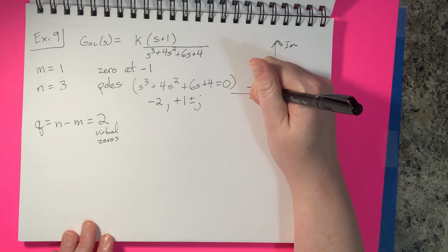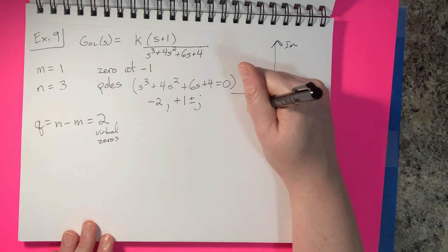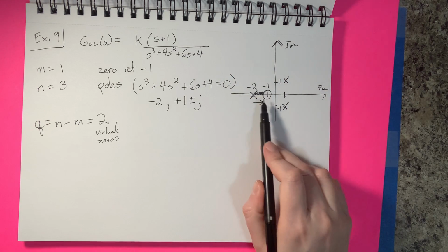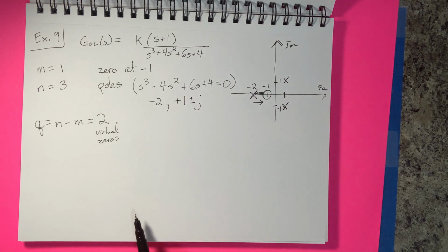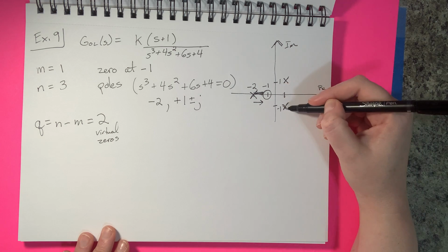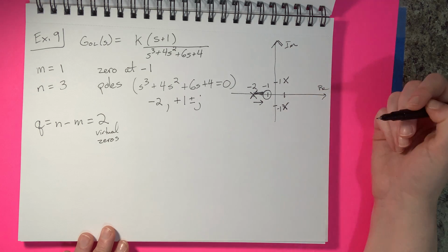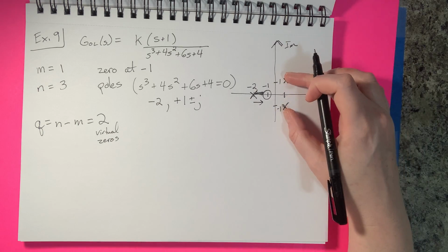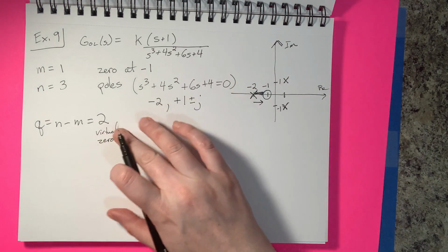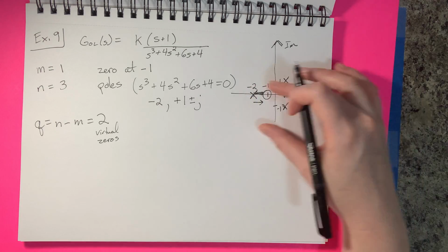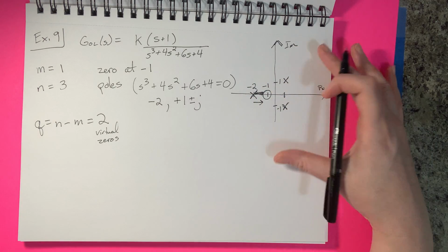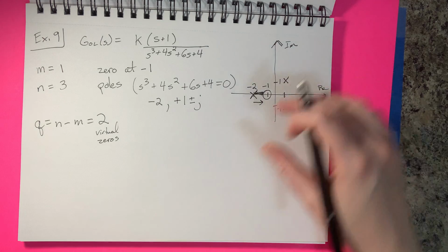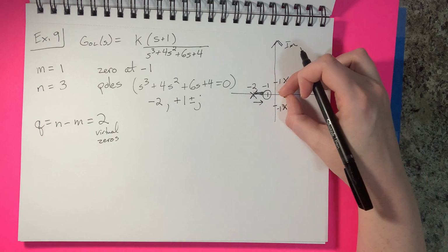Well, this makes sense, and so this pole would move towards this zero, so we have our direction down. We now have these two poles right here. What happens when we don't have any? We have 2 virtual zeros, we know, but we don't have any zeros for them to move to. Well, we had an earlier example where these moved to the axis and then they deflected off.